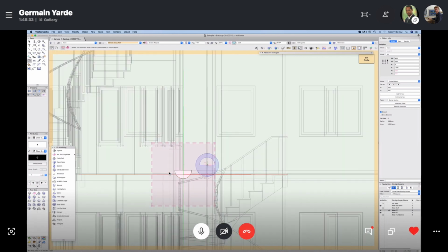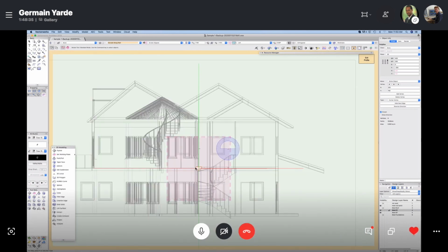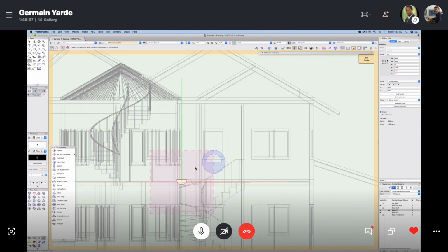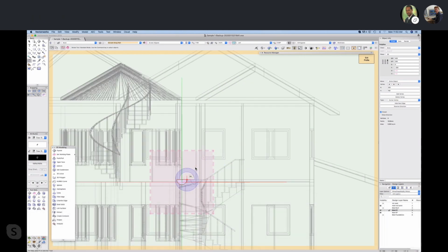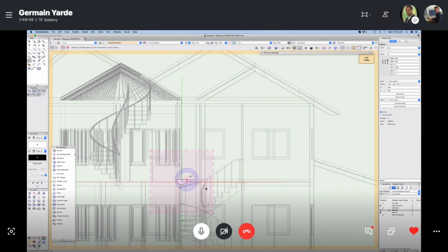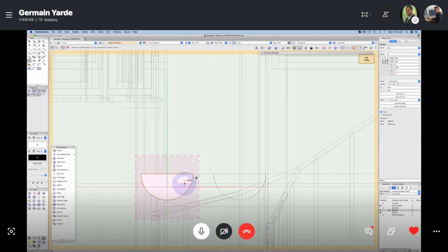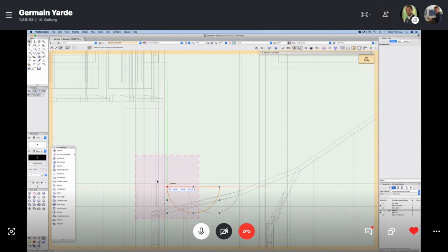Good, so you should be able to see that if you click and move it. Don't worry about it being on the wrong layer. Once we move it to the roof layer, it will snap up to where we need it. So where to move it? Zoom in a bit, grab the corner, so click X, yeah, click X, grab that corner and just snap that to the red and the green axis. There we go. And snap it to there. Cool, now that looks right to me.